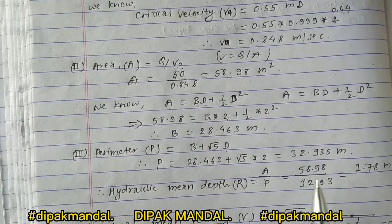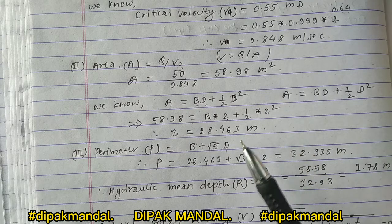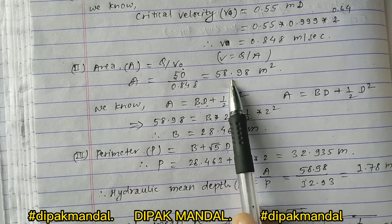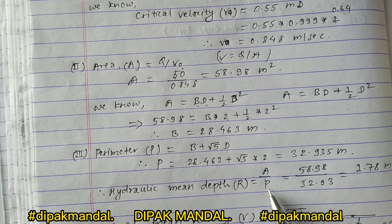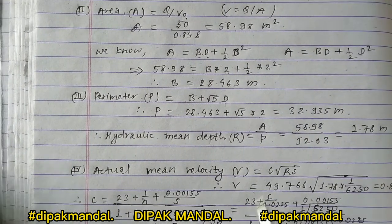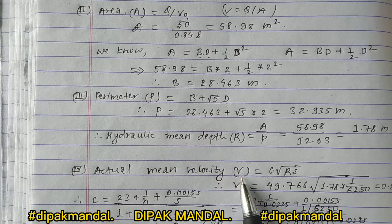Okay, now we already know the values of A, P, B and D. So simply we can calculate the hydraulic mean depth, that is, the value of R. As we know, the hydraulic radius R equals A by P, area by perimeter. So we have area equal to 58.98, we have already calculated, you can see, and the value of P is also calculated, 32.93. So we get the value of R equal to 1.78 meter.